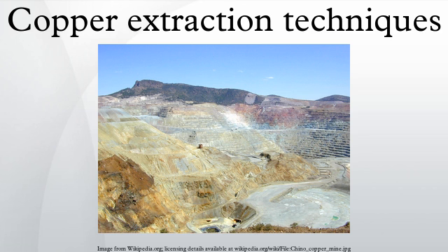Electro refining. The copper is refined by electrolysis. The anodes cast from processed blister copper are placed into an aqueous solution of 3–4% copper sulfate and 10–16% sulfuric acid. Cathodes are thin rolled sheets of highly pure copper or, more commonly these days, reusable stainless steel starting sheets. A potential of only 0.2–0.4 volts is required for the process to commence.